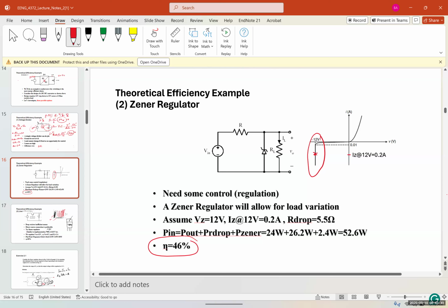What is our other option? Another option that we can use is, do you remember what other options we had in electronics? How did we regulate the voltage at the output of a bridge rectifier? Do you recall what we did in a bridge rectifier in the lab specifically? We had a transformer, then we had the bridge rectifier. After that, we had a capacitor, and the final piece was a voltage regulator. You remember the IC that had an aluminum piece attached to it, the 7805, 7804, or something like that.